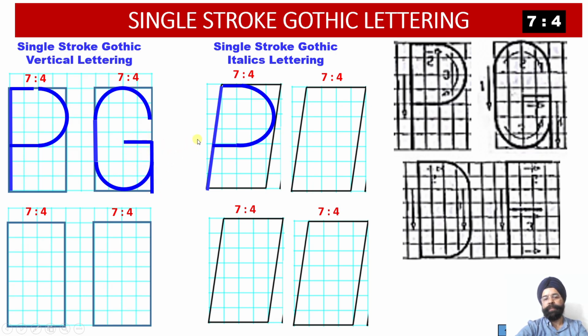So this is going to complete your G. The same thing we can do in italics. Just see, upper cup for 2 blocks, lower cup for 2 blocks, vertical line becomes inclined. Then you draw this inclined line up for 3.5 blocks and draw the horizontal line. So this completes the construction of the italics G. So this was the vertical G. This is the italics G.